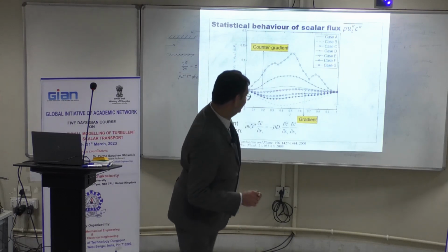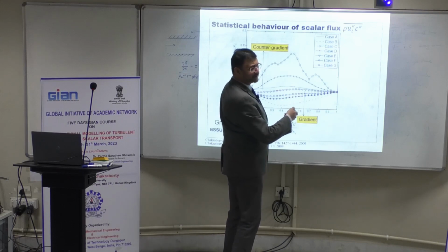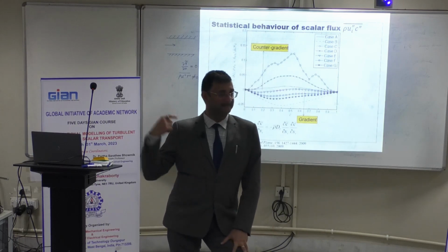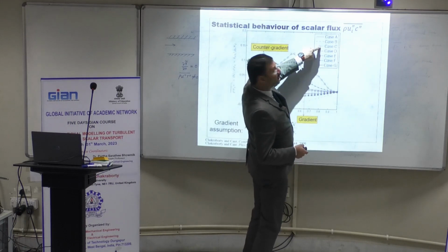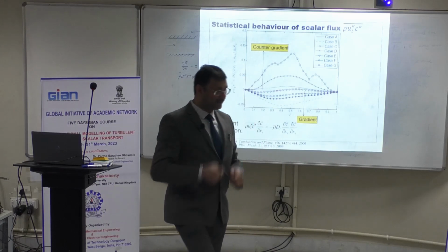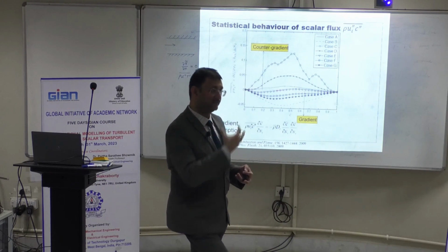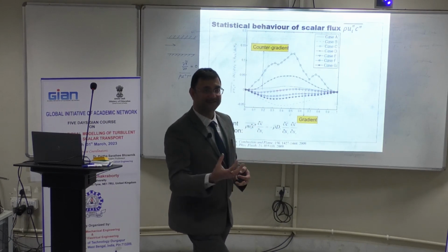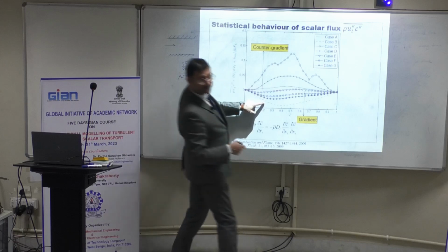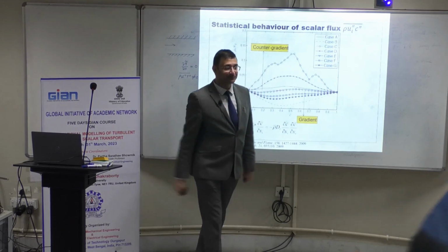Now, another thing. Case B. All of these cases, case C onwards, all of them had a heat release parameter of 4.5 from the table. This one has a tau value of 3, so that means heat release rate strength is lower. The velocity jump is not really heat release rate strength, it is basically the extent of velocity jump because of thermal expansion, which is relatively weaker in that place. So turbulence actually dominates more easily, and you are seeing a significant amount of gradient type of transport.